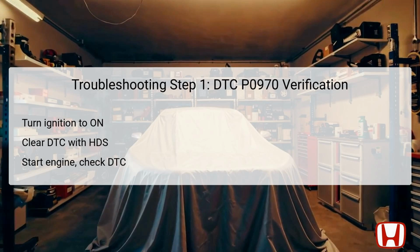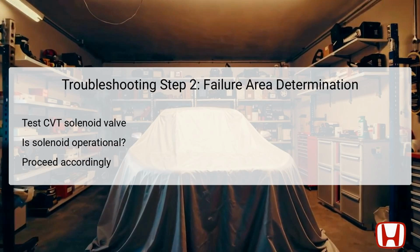but further investigation may be necessary if freeze data is available. In the second step of troubleshooting, the technician needs to determine the potential failure area, specifically focusing on the CVT clutch pressure control solenoid valve. Begin by testing this solenoid valve to see if it operates properly within the electrical circuit.